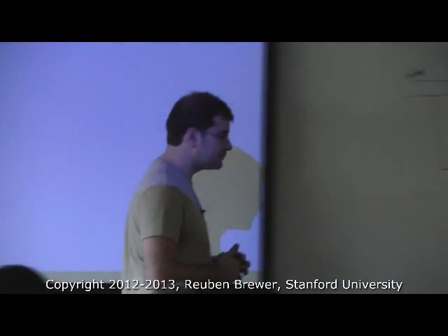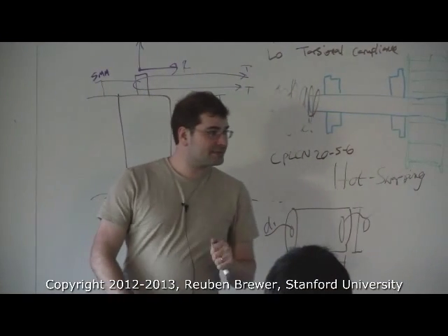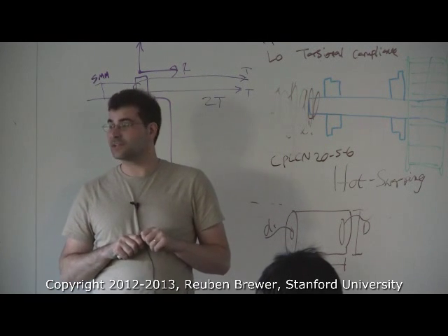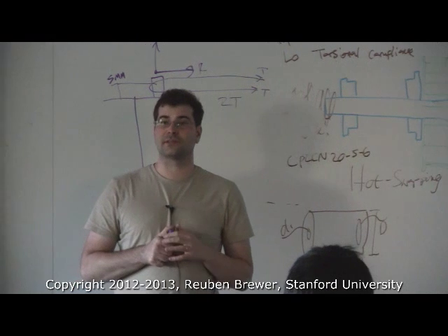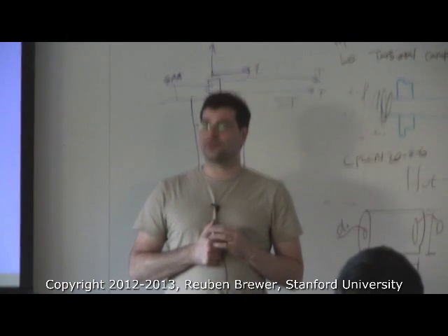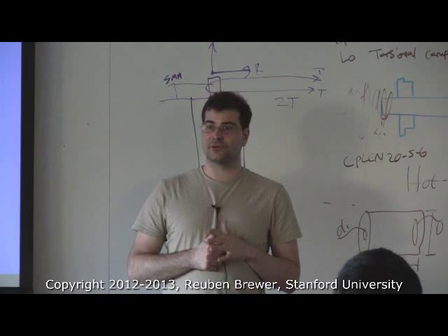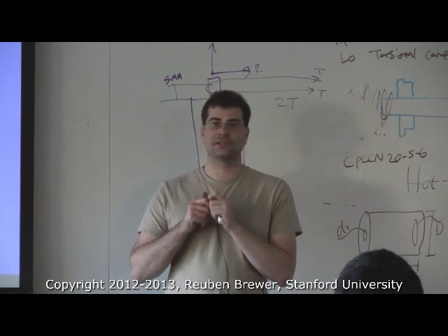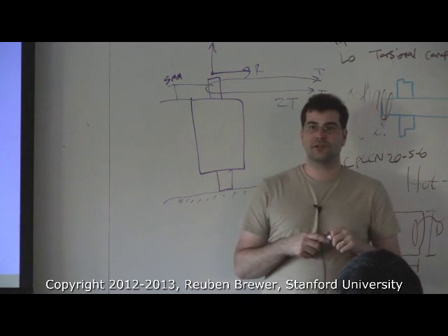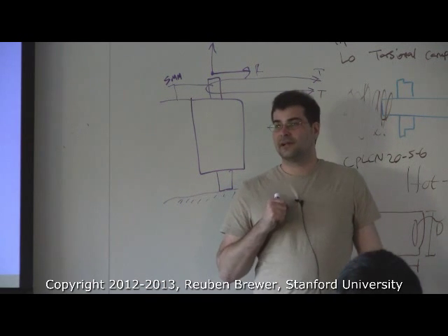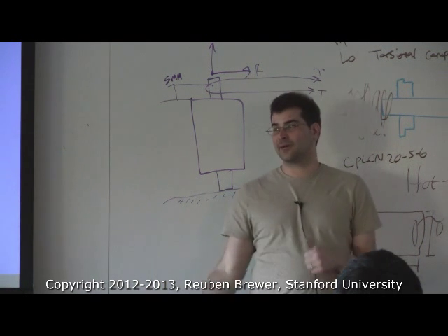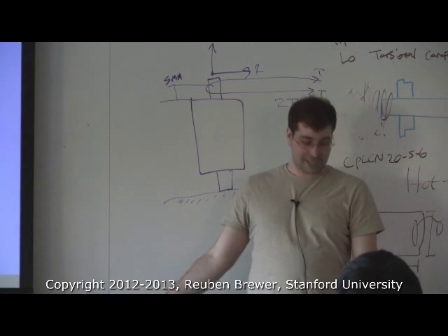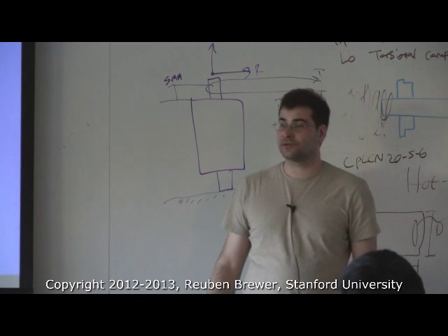That concludes DC motors. Now just real quick, on Wednesday we're going to talk about how to measure things precisely. If there's one lecture you should not miss all quarter, it is Wednesday. I notice a lot of people don't know how to use calipers properly, which means all of your measurements are wrong. If you want to measure the right shaft, you don't have to sand it. I saw some people using calipers. You don't want calipers for that, you want micrometers, and I'll show you how to use those on Wednesday. We have them in the tool chest, but no one's been using these wonderful, beautiful tools because they don't know how to use them.